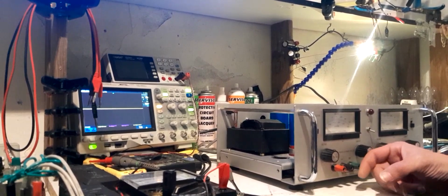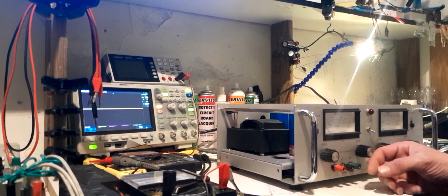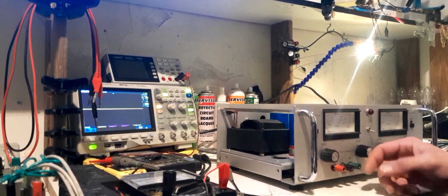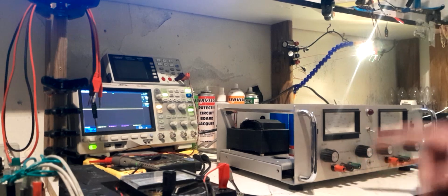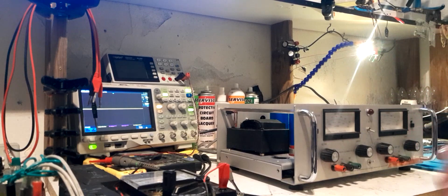If I put a huge capacitor across the TL431's anode and cathode, you have to wait for the RC time constant. The current's got to get through the R and then charge up the C, which takes time. And as I explained, if the reference is low, the voltage will be too high, and that will lead to overshoot, basically.